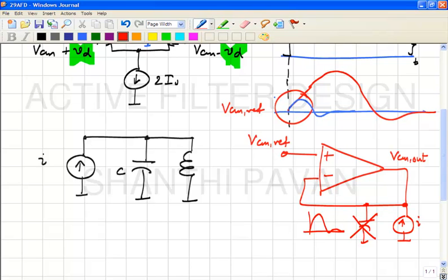In the open loop, it will have very high impedance, and then when you put in closed loop, it will be that impedance times 1 over 1 plus beta. It's not entirely correct, but that's for those of you who have experience with loop gain and its effect on output impedance. Loosely speaking, the closed loop output impedance is nothing but the open loop output impedance divided by the loop gain.